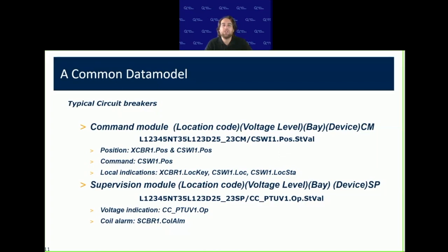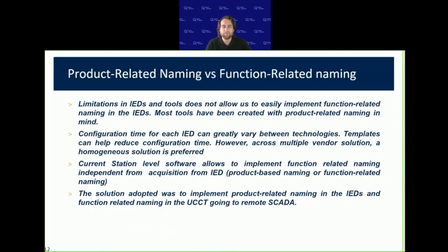Same for the supervision. This will change based on the type of circuit breaker and voltage level, but as I said, those are standardized. There are five or six types of low and medium voltage circuit breakers, so it's easy to regroup and have different kinds defined under the same points as always. Those are defined under the supervision model, and as you can see, the logical device is almost identical when we're referring to the same device.